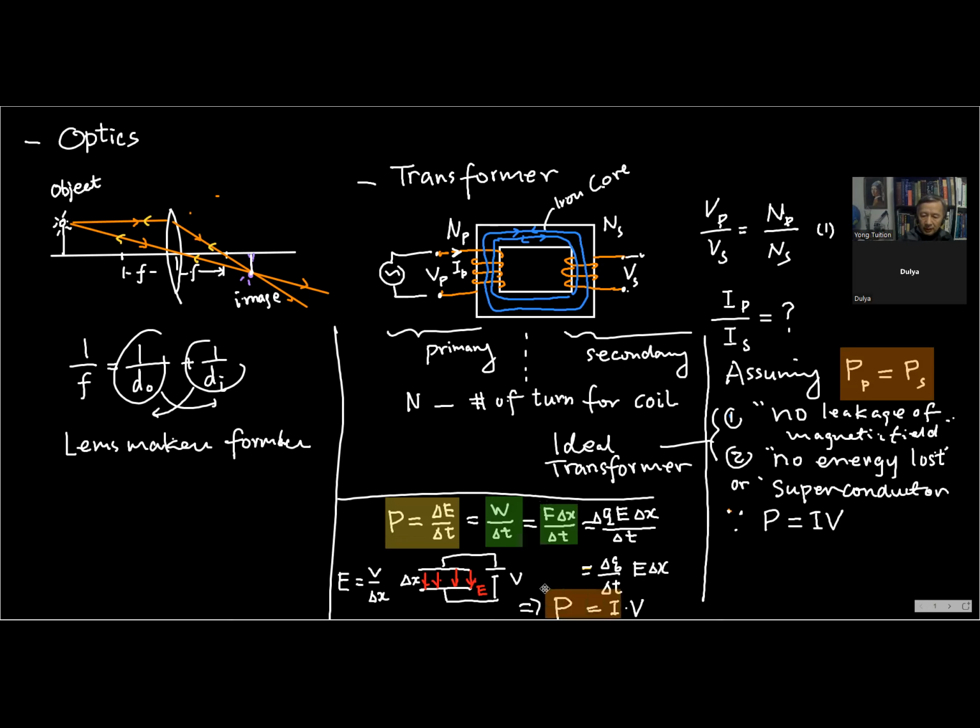This one. Can you see that? Yeah. Which is the formula written down here, all right? So if we use this formula to assume that there is no power loss, the input power will equal the output power, or primary power will equal secondary power, right? So that will allow us to write this formula here.